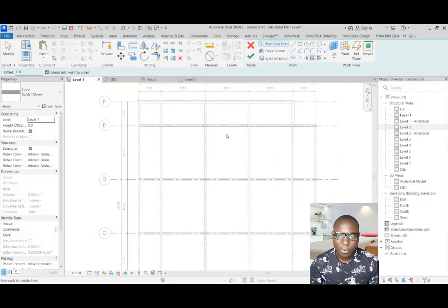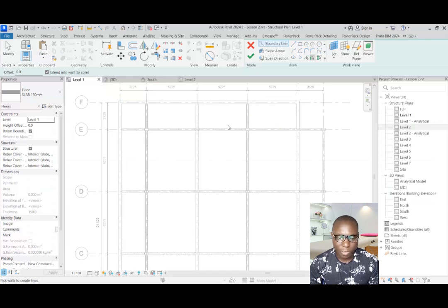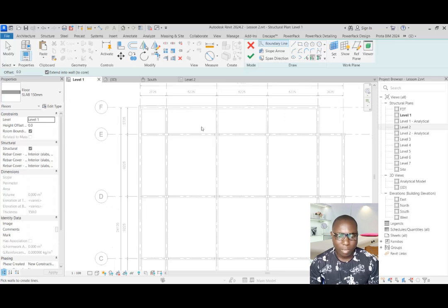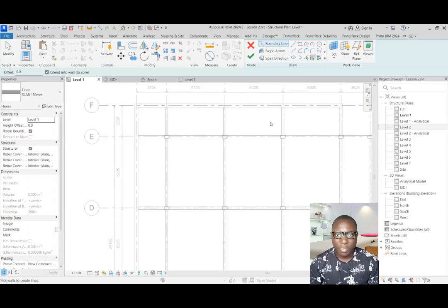So now we start to place the reinforced concrete slabs. You can actually place the slab using various options. Either you can draw a rectangle using 2 points, or you can use the pick support, which is the beams. You can pick the beams, but this is a shear wall, so it seems to be a kind of uniformly distributed load. All right, so what we do, we can use these options.